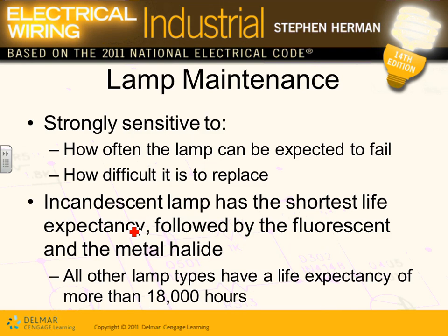Okay, the last thing, guys, is lamp maintenance. It's a big deal. How big of a deal is it to maintain the lamp, guys? Strongly sensitive to lamping. Lamps can be expected to fail, so you have to do re-lamping. How difficult is it to replace these lamps? Do you need a crane to go there, or what do you need? A ladder? What type of tool do you need to replace these fixtures? So you don't want to put them in a high place.